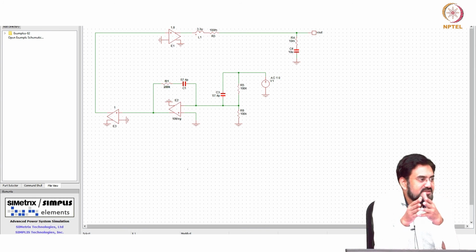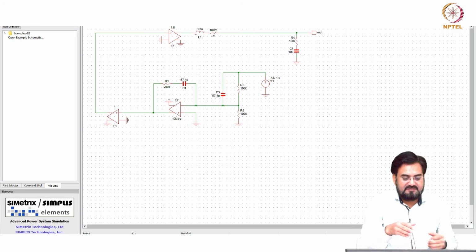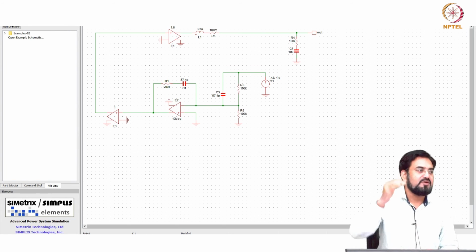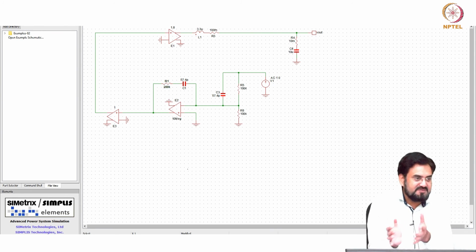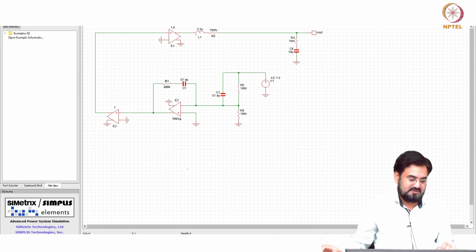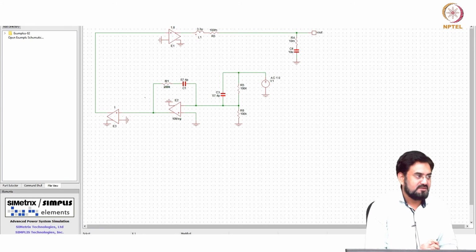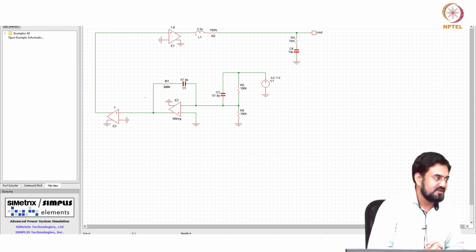So then in that case, tan inverse omega UGB over omega Z2 should be your phase margin. But if let us say that is not going 180 or close to 180, let us say it is going only 170, 175, then that much phase you have to add there. But in the worst case, it will be the phase due to the omega Z2 phase margin. You cannot get worse than that actually, because you know the maximum phase shift LC can give is 180, not more than that.